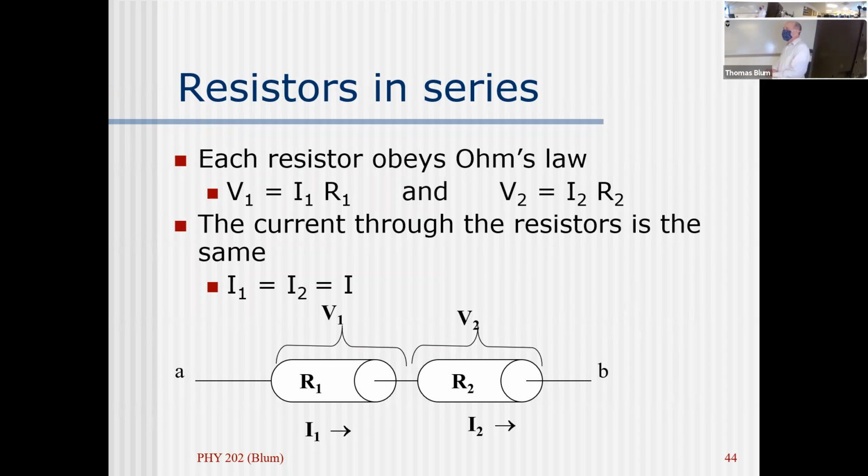Okay. So things in series, those resistors were in series, they see the same current. Current is the charges that are going by. Any charge that went through 1 has to go through 2. The charges can't accumulate between the resistors. That would cause a lot of trouble, and they just don't do that. They're going to go from one side of the battery to the other side of the battery. That's what they're doing, and they don't stop along the way.